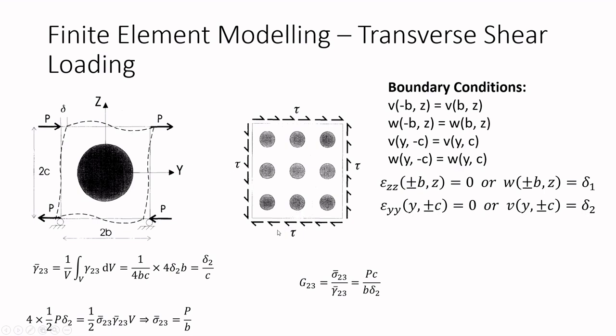In this particular analysis, this condition is not imposed, and to know the displacement over these boundaries, a bigger space of 9 fibers has been considered. By applying the shear stress on the boundary, the displacement around this RVE is measured, and those displacements are imposed in this model as the input to specify boundary conditions.